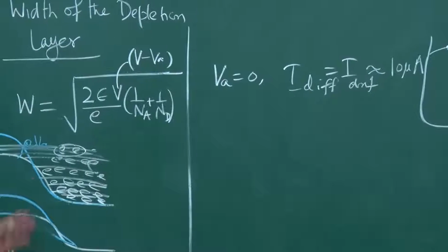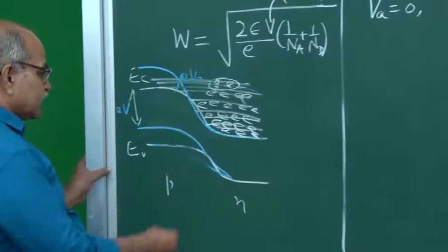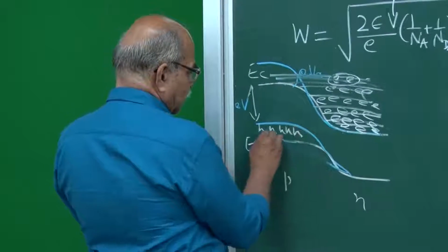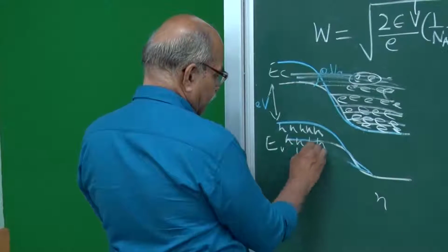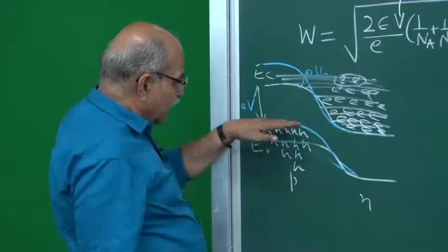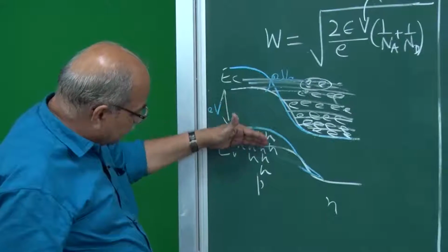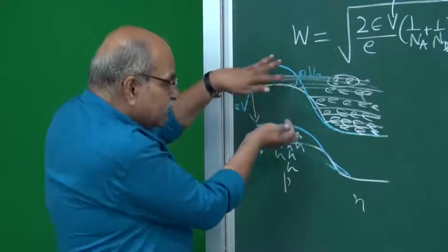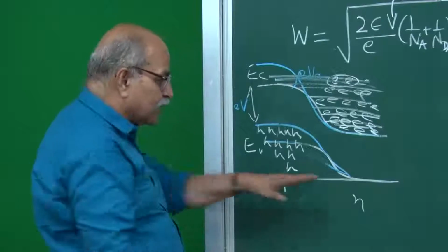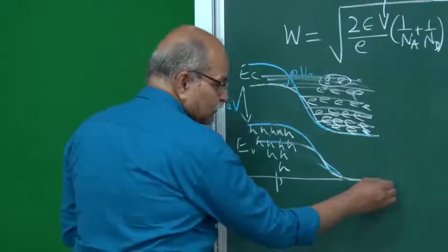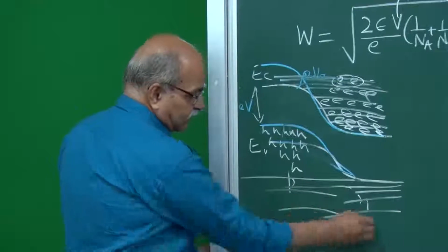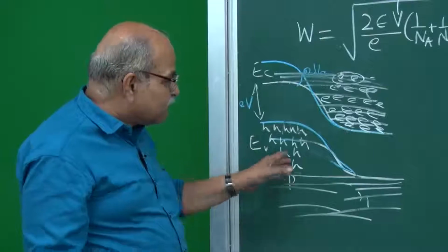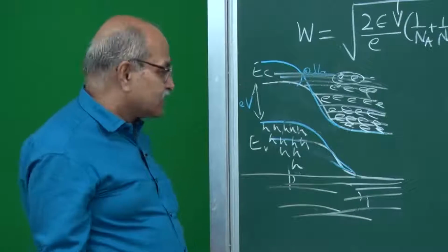Nevertheless, similar is the story here, the majority carriers here are holes. As you go away from this point, you have smaller and smaller population. And you have lifted everything up, and anything above this line is not allowed to go here. Your valence band states are here. So, anything above this is not allowed to go here, and then you are lifting it up. So, that diffusion of holes also decreases naturally.